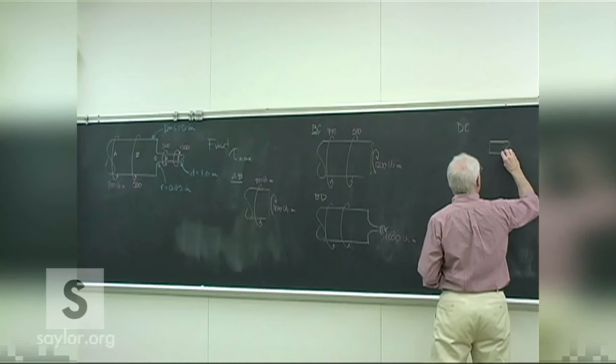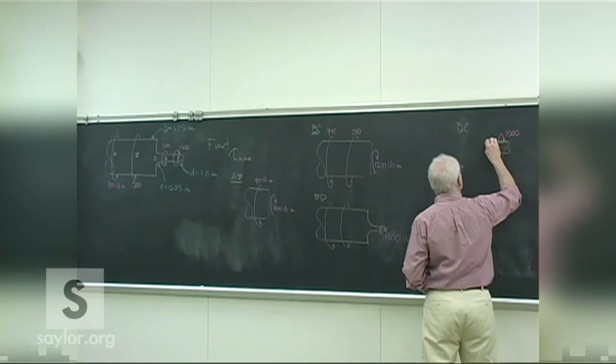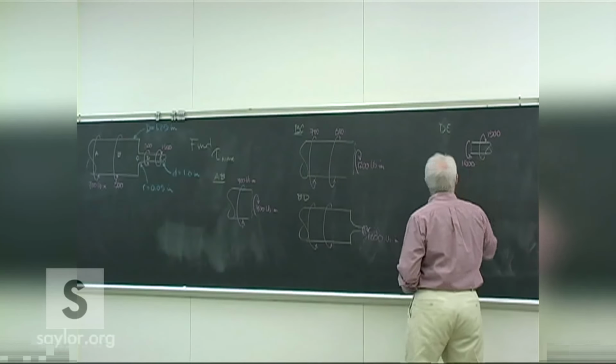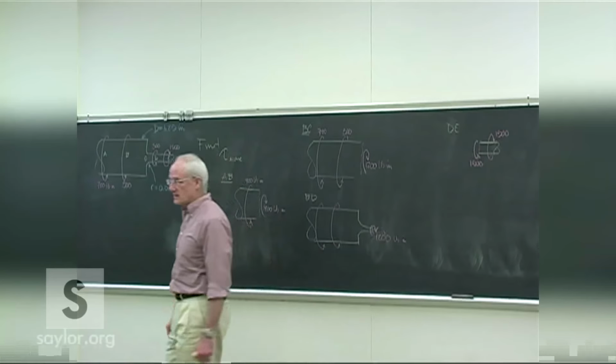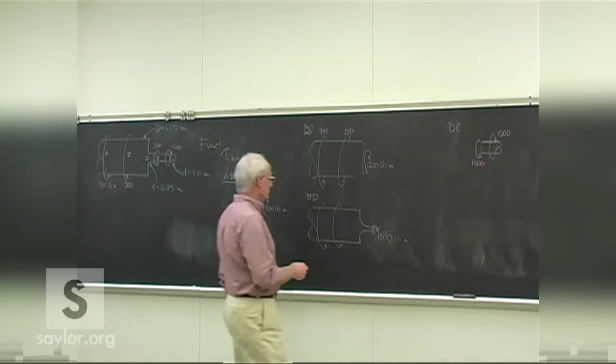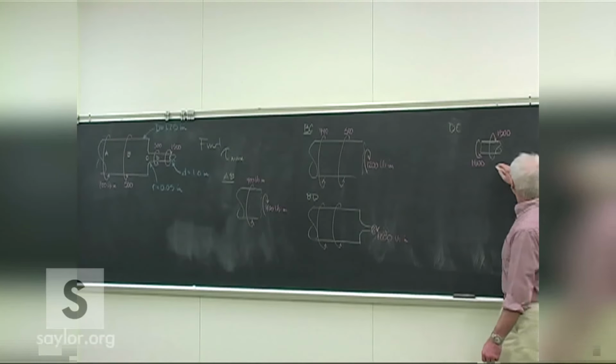We have the 1,500 there. We're not concerned about the direction. We would be if we were looking at the angle of twist on this entire shaft, but we're not. We're just looking to make sure we're under the stress limits. So it looks like two areas of big concern.